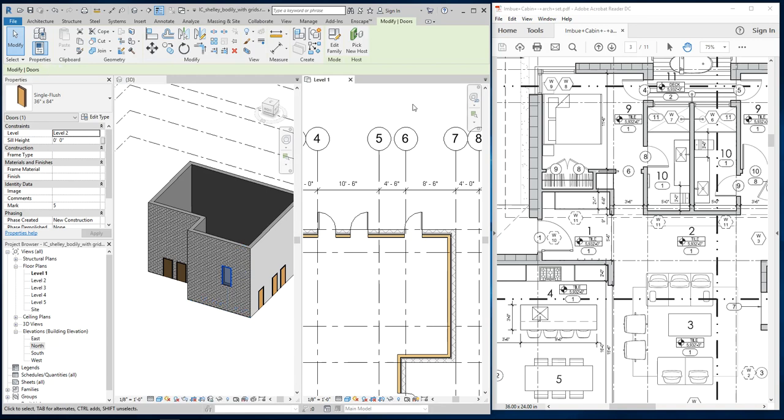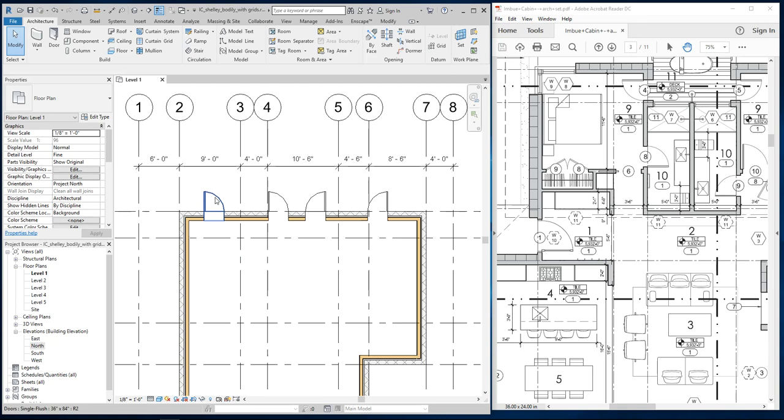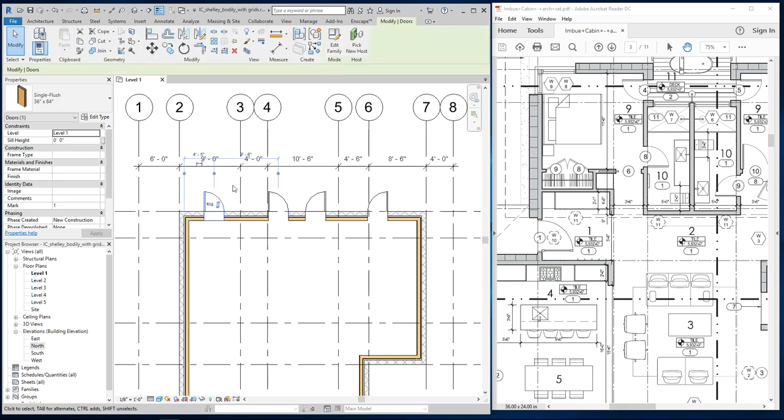Okay. So let's see how many door types I have in here right now. Door types and wall types are kind of similar in that when I opened up Revit, I had maybe 10 different wall types. They were all defined differently, with different wall assemblies. Each element in Revit has a set of properties associated with it that you can change. They're kind of tailored to that object. So walls have a top and bottom constraint, and then they have a wall assembly system where we have to define the different layers of the wall assembly. It's appropriate for walls, right?